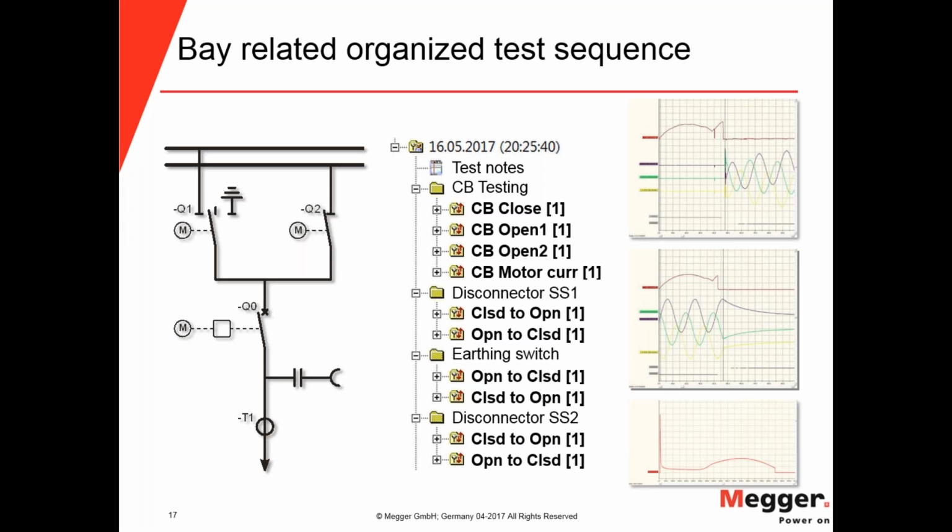So this is an example of a test plan that this customer built up. It's very organized. You have circuit breaker testing in one folder with your close and open, and then open for system 2, and you have motor current measurement, which you actually see the recording examples of here.